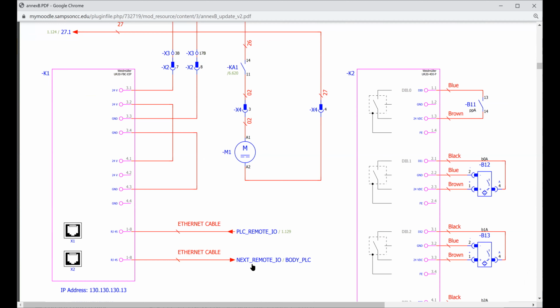They can change around. All of them have double Ethernet jacks on everything. It goes kind of like this. The PLCs have 2 Ethernet jacks on them, and then the remote I/O also has 2 Ethernet jacks. So it's an easy way to daisy chain everything and not have to have a central Ethernet switch that everything goes to like a hub, you know what I mean?